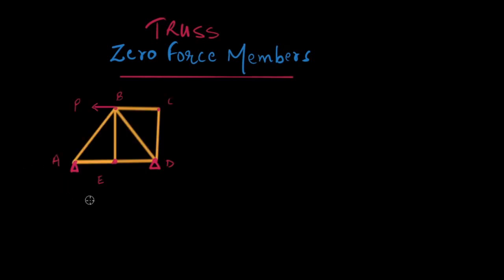Now in the figure, you can clearly see different members which are joined together by the pin joint to form a truss. The members, I'm calling them struts, are different from columns. Columns undergo different kinds of stresses when they are under load, like compressive stresses, tensile stresses, and bending stresses. But struts have no bending stresses. Hence, the member undergoes only compressive and tensile stresses. In other words, the member in a truss is under direct compression or direct tension.